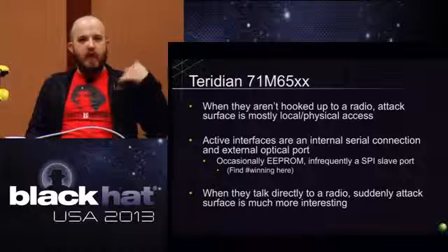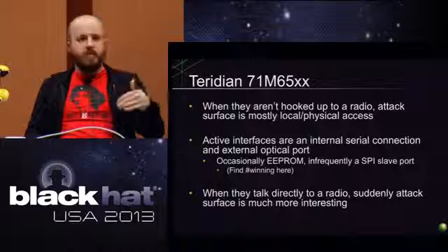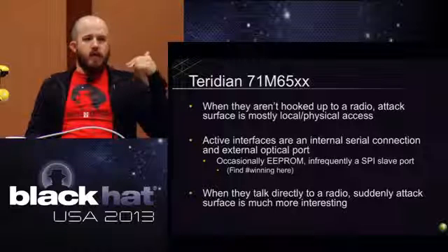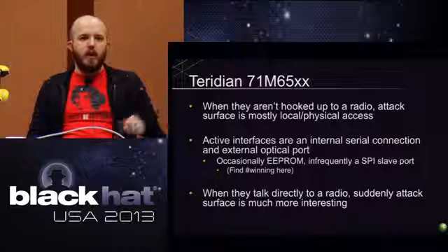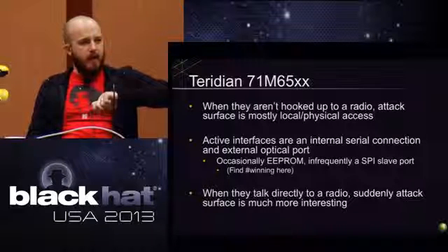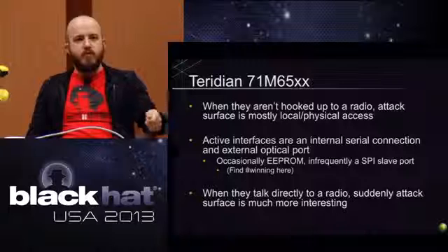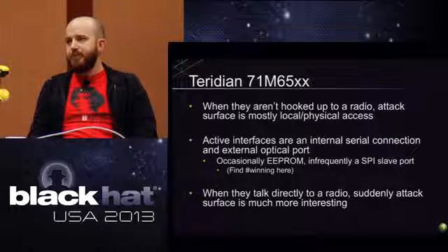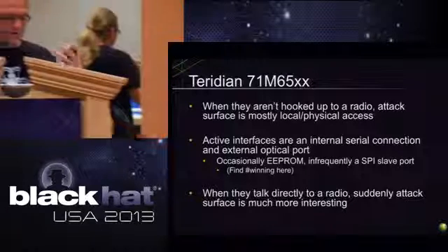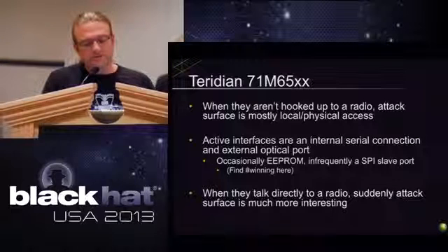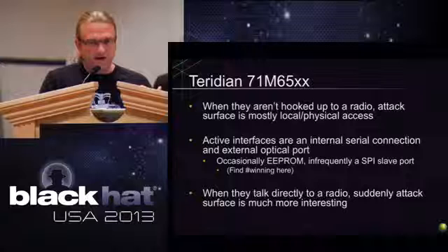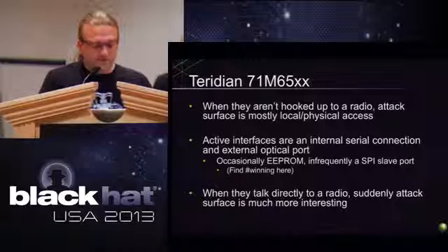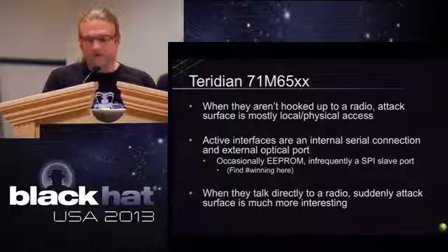Or it could be doing straight pass through, and the Teridian chip itself could be speaking something like ANSI C12.22, which is the one for network communications, and then you've got actual packets terminating inside the Teridian chip itself. So when they're not hooked up, you have to have physical access to be able to pop this. As soon as they're hooked up to any sort of radio interface, now you actually have a valid remote attack vector, which is logical, and it's not really jumping anywhere from where we're comfortable.